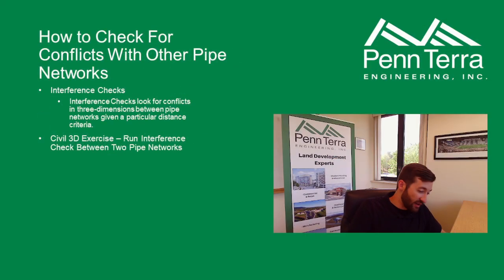Okay, last thing we're going to go over today is how to check for conflicts with other pipe networks. This is somewhat limited in that it can only look between pipe networks like a storm and a sanitary, or if you have, for some reason, 2 runs of storm or sanitary crossing each other, you can check that. You can't check for crossings with other utilities that aren't modeled as pipe networks, like water or something, gas maybe. But it is useful for checking between your storm and sanitary, which we have to do pretty often.